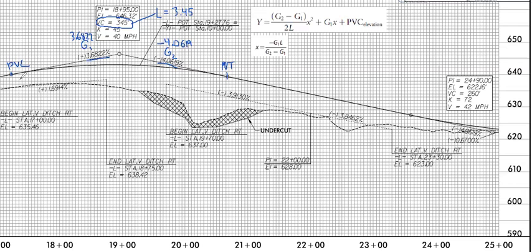In terms of the stationing, we're going to take the PI station, 18 plus 95. That was our reference point that we were given for the problem. We're going to subtract off half the length from that station because it's L over 2 between the PVI and the PVC. So it's going to be half of 345 feet, or 1.725 stations, or 172.5 feet.